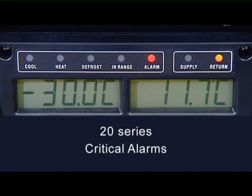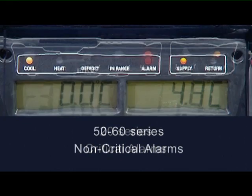When a 20 series alarm is activated, the alarm code will flash alternately with set point while it is active. The 20 series alarms, when active, have to be immediately corrected as the unit will shut down or will not be able to properly run anymore. The red alarm light will be illuminated for these series of alarms.